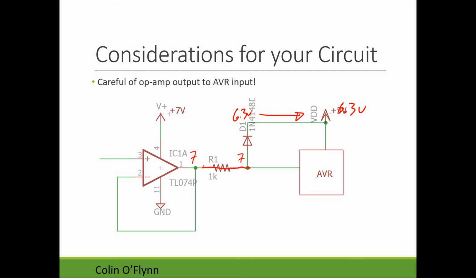It depends on your exact system, but to avoid that, you really need to ensure you have a resistor in there. And then now you no longer have this issue. You don't have to worry about your AVR blowing up.